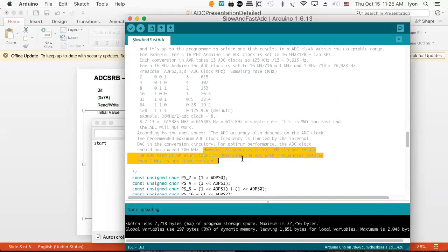As far as I know, it could be down to 9 bits, 8 bits, 6 bits. Take your pick. Who knows? And not characterized means they don't really care what you do if you want to do that. It's not going to blow anything up, but don't expect it to give you a full 10 bits worth of accuracy.